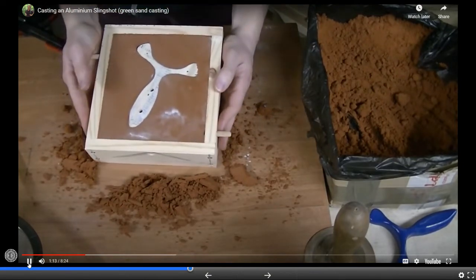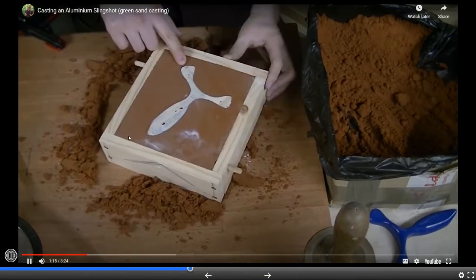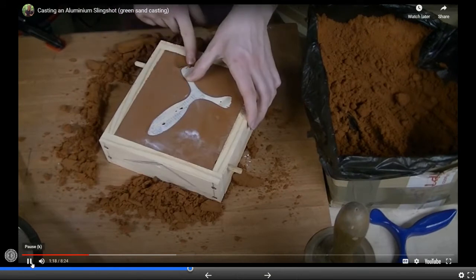All right, and so now he has created his mold. Because the pattern had moved slightly. So another thing is that you saw he said the pattern had moved slightly. This is called mold shift. And it often happens when you're removing the pattern from the mold. You can maybe shift it here, shift it there, and then that actually changes your mold, which is kind of what happened to him right here. So that's one thing that you have to watch out for when you're doing the green sand casting process.